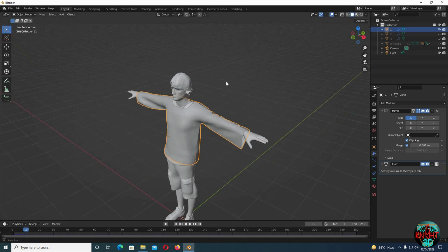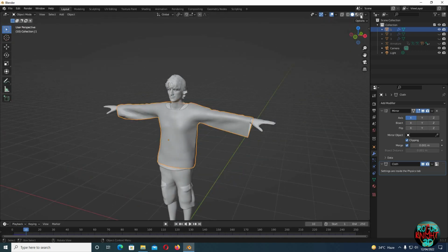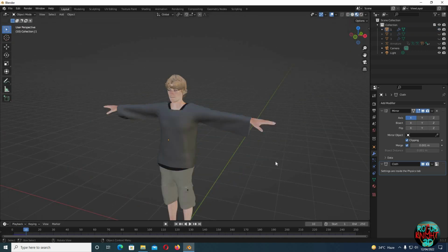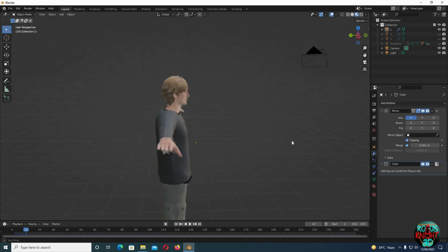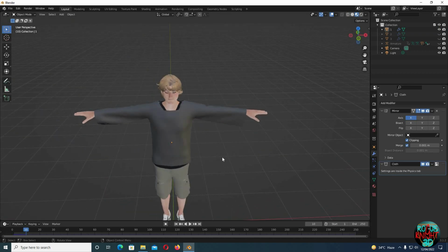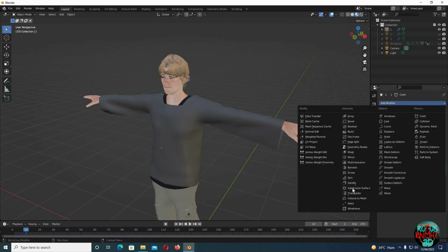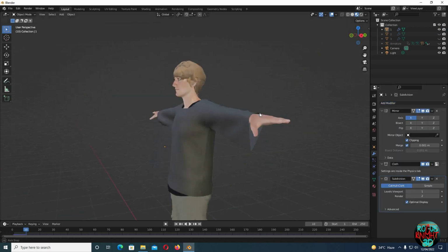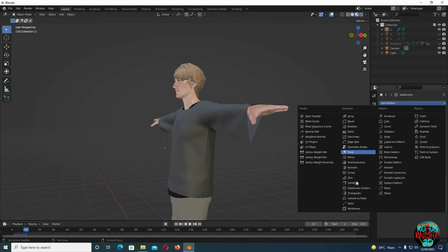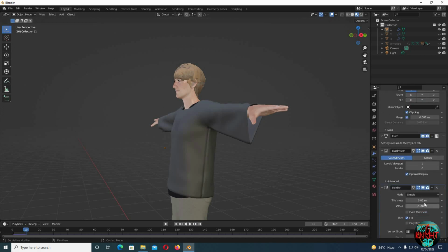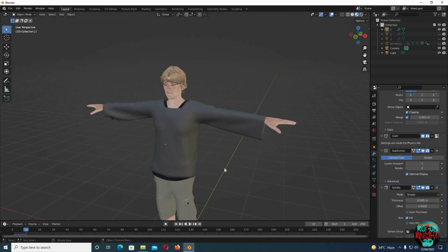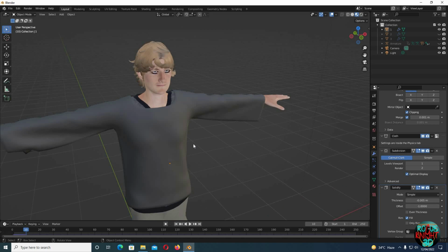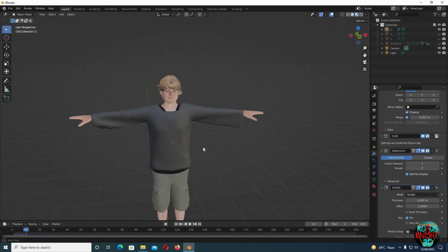We face this problem because our cloth or its edges used for sewing were colliding or just too near to our mesh, and the sewing couldn't be done with our mesh in the way. Well, we have our shirt. We will now be bringing in a subdivision modifier and also will bring in a solidify modifier as well. Reduce the thickness to negative 0.005. It's looking beautiful, but it needs more styling and also some extra material tweaking as well.